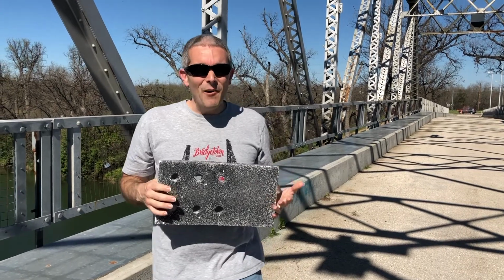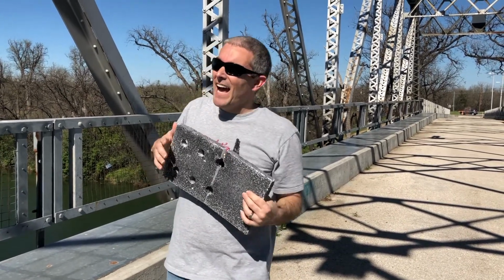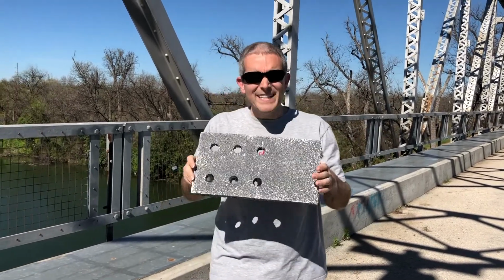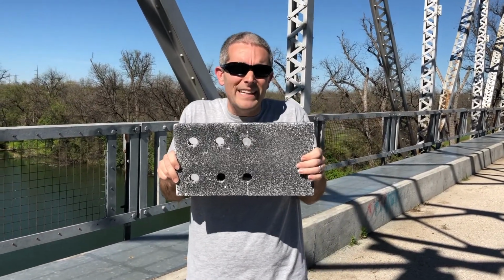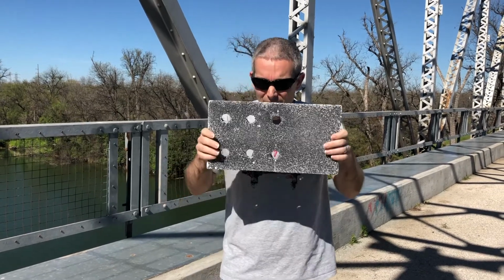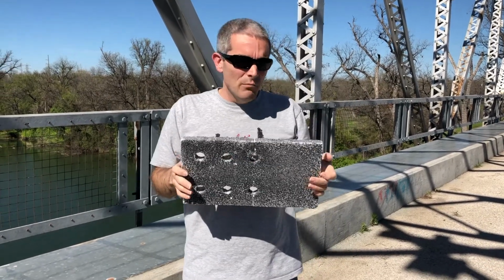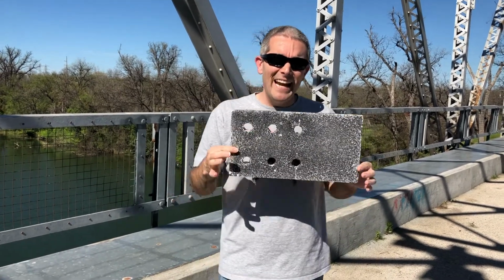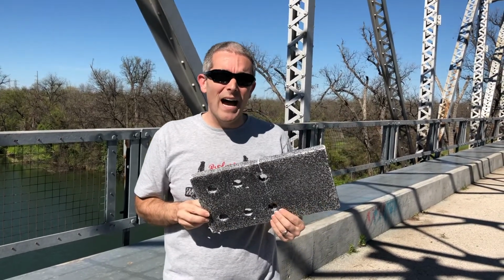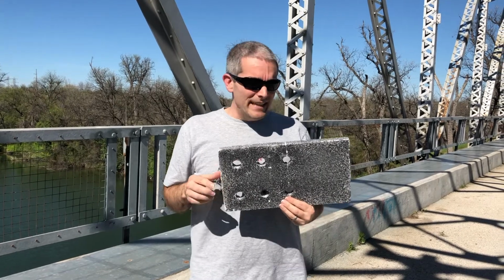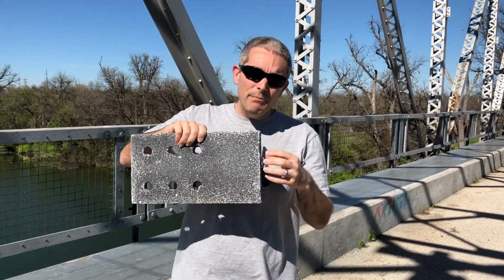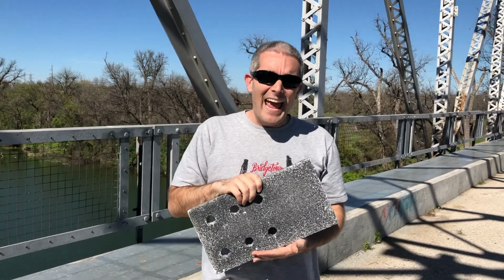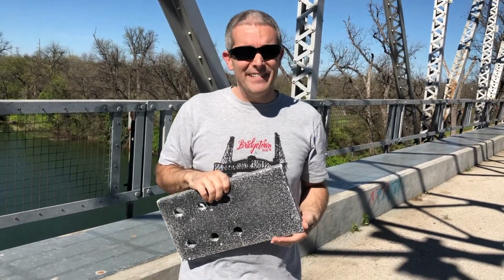All right, so now we don't always have such a complicated connection geometry as we do here on this truss bridge. So I kind of simplified it. This is kind of a typical plate-to-plate connection. So about 6 bolts. We're looking at an 8-inch wide by 1-inch thick plate, and it's connected to a 10-inch wide by 1-inch plate. Now, as we can expect, as we pull on this member, we're expecting the 8-inch member to fail first. And we want to come up with the capacity for that.